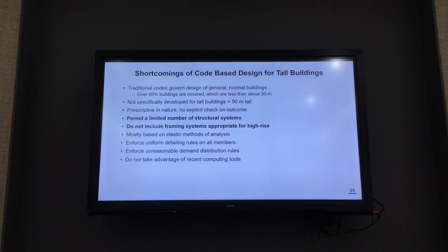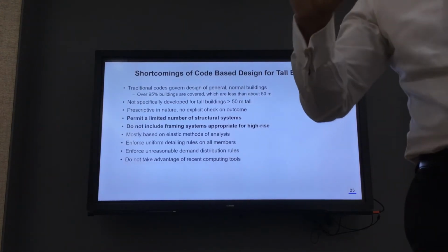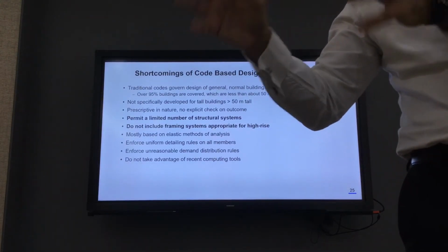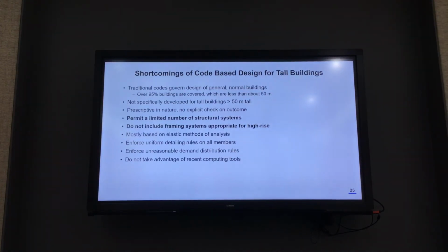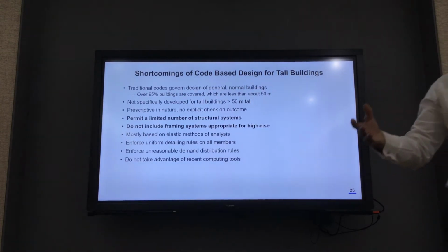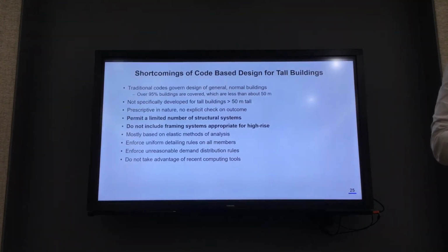But in reality, it is very, very difficult to do that because core walls are so stiff that they can take about 80% to 95% of the loads. So if you try to design the frame for 25%, you have to increase the reinforcement for no reason, just to follow the code. Useless money spent or useless column sizes increased because we have to follow that provision. Nobody likes that provision. And if you use performance-based design, you can prove that core-only buildings are fine too, right?